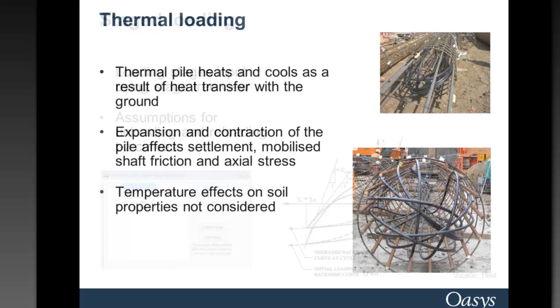Then the third update to the program includes the ability to analyze thermal loads on the pile. So, for example, where thermal piles are installed in the ground, it seems to be becoming increasingly popular recently, and these piles are similar to bored piles, only they include pipes that are attached to the reinforcement cage, plastic pipes that water can then be circulated through in the pile at a later date once the pile has been completed and concreted.